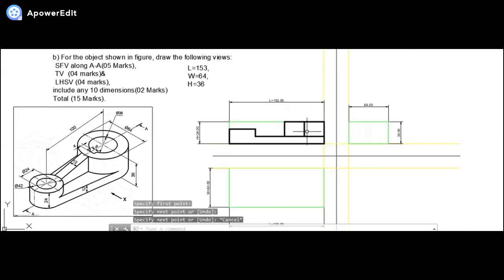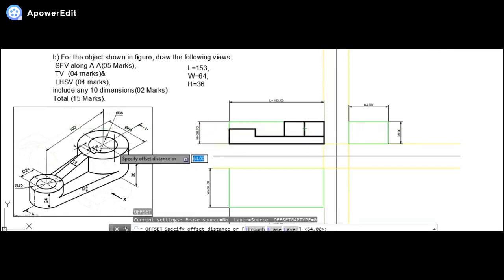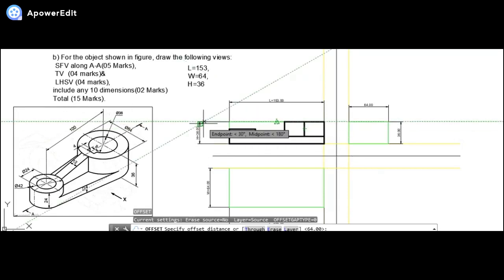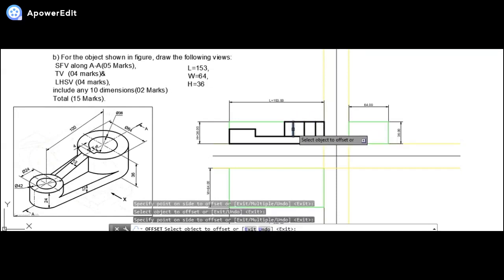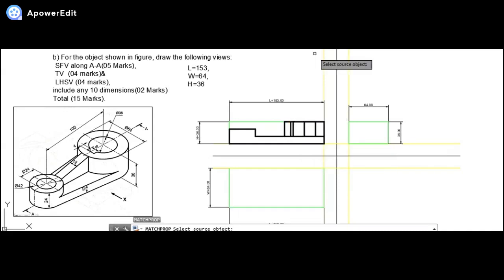Once we are done, now the center line over here, first center line, at what distance will it be seen? There are two edges now. The inner edge we will be drawing later on, but phi is 36. So from both the sides at a distance of 18 each, I can show it over here, I can show it over here. Beyond this, even from here at a horizontal distance of 4 mm, I can see the edge over here. As of now, I can simply make those hidden.